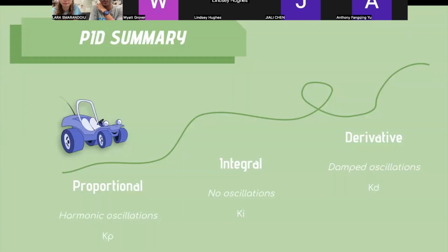And one quick thing that I also want to mention is that for the derivative controller, we've introduced these in the context of something continuous, right? But obviously when you're doing your Arduino measurements, you're taking measurements discretely. So all the derivative means in that case is a subtraction. You take successive differences of your errors, right? So you just subtract one measurement from the next, and so on. That's all that means.